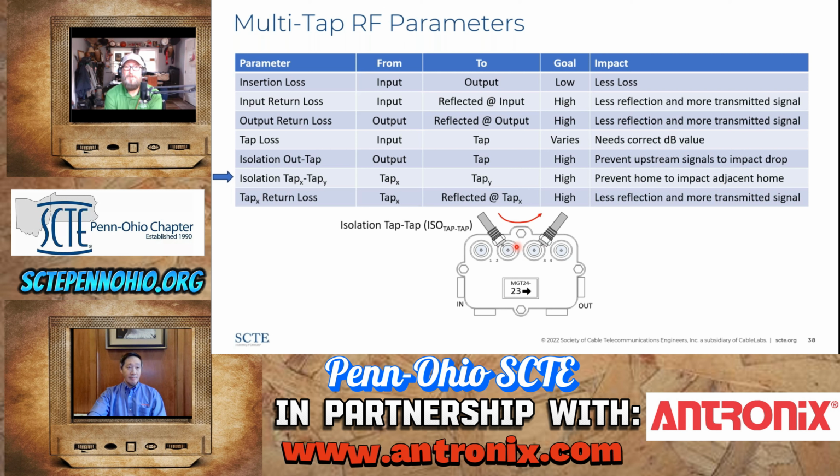So it's a way of protecting premises from each other, quite frankly. Unfortunately, that doesn't prevent that noise from being funneled back through the splitters, combiners or directional couplers into the upstream path, but it would be less impactful to the other customers on the tap. Correct.